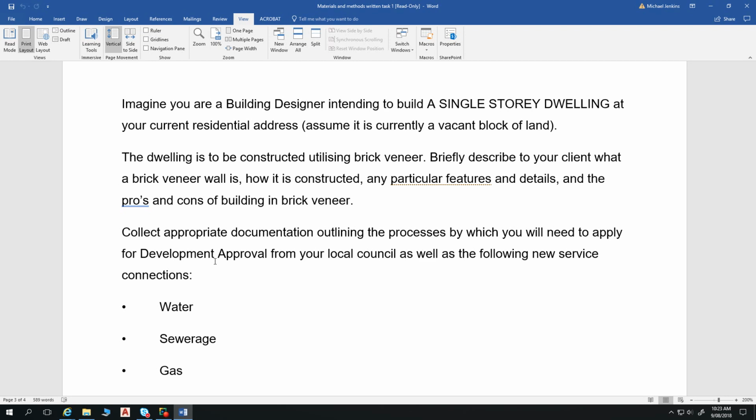So this is where our water can come out. So it's designed that if water gets inside our wall, these ties slope back towards the wall, so that any water gets directed down that inside face of the brickwork, hits our damp-proof course, and goes out our weep holes. We have to ensure that that works.